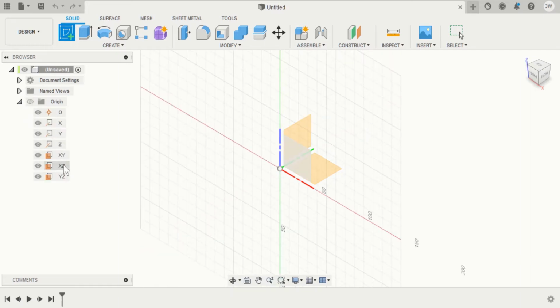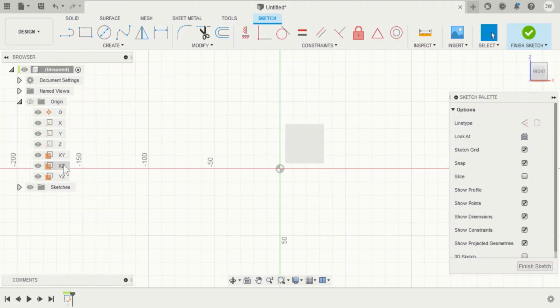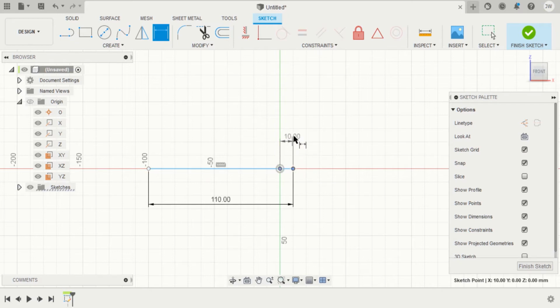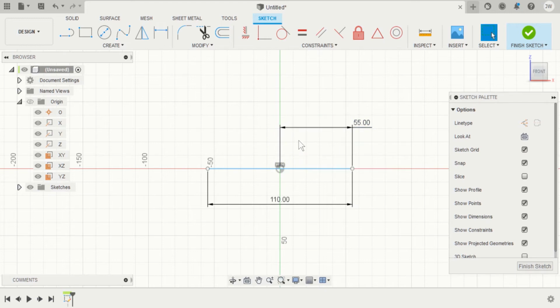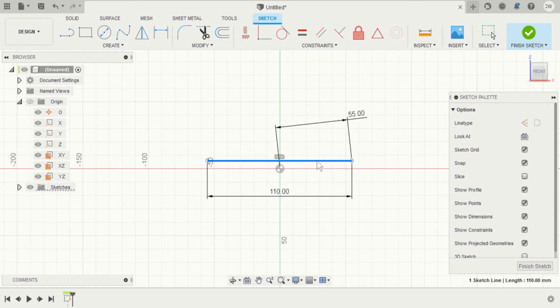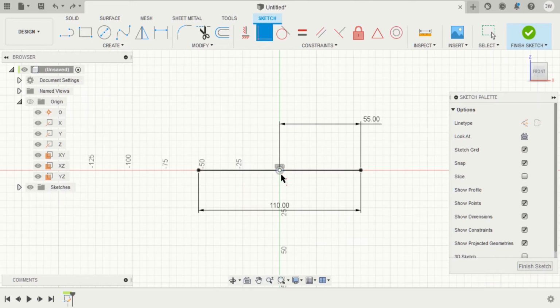and draw a horizontal 110 mm long line, which we place symmetrically in our sketching environment, with 55 mm distance to the center. We also need a coincident link between the line and the origin to fully define the line. A 15 mm long vertical line, and a 70 mm long horizontal line connected to it, represent the first part of the handle for the screwdriver.